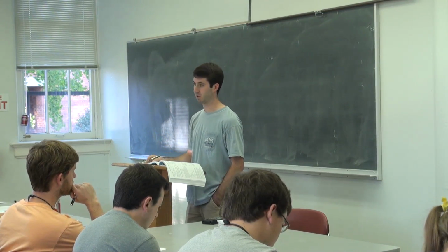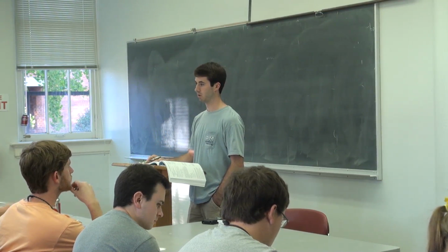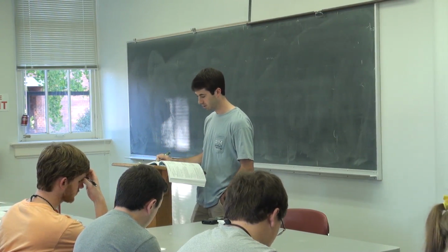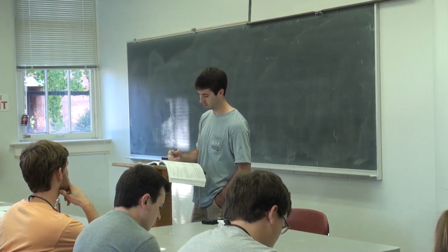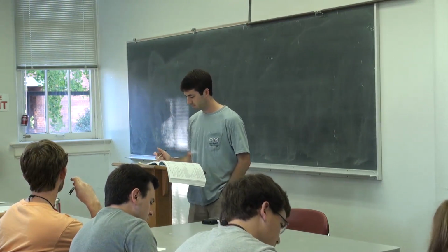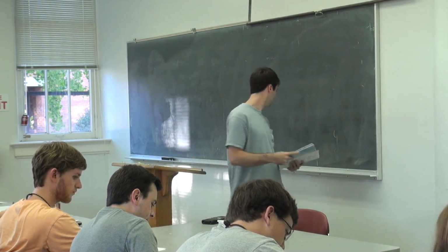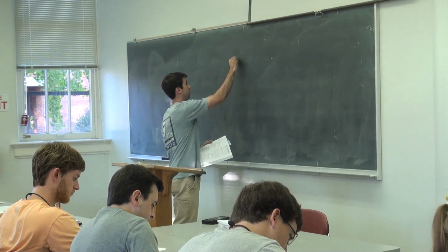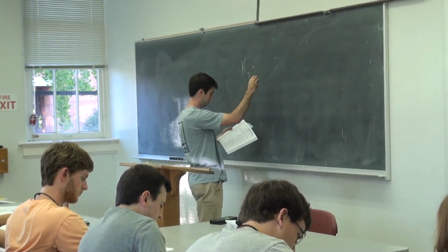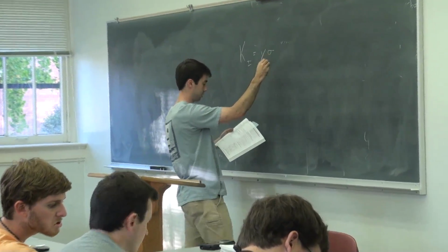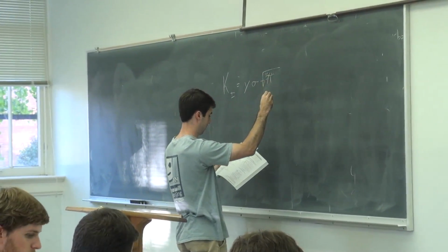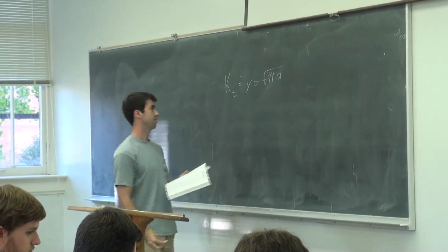Crack propagation just means the crack's already there. Basically, what stress intensity factor do you need to keep it from growing? So if you take what information you're given and plug it in this equation, you would get, let's see, K_I equals Y times stress times the square root of pi times a.